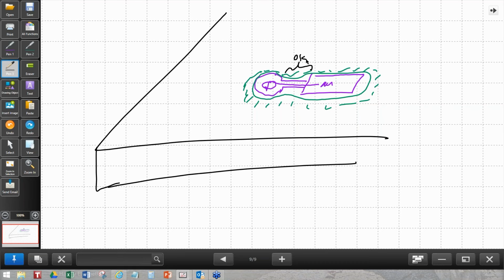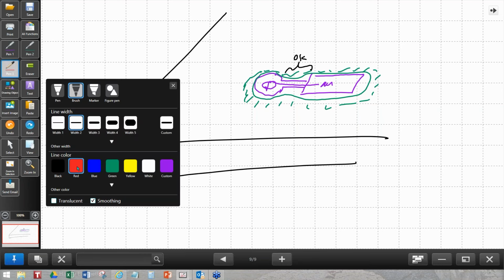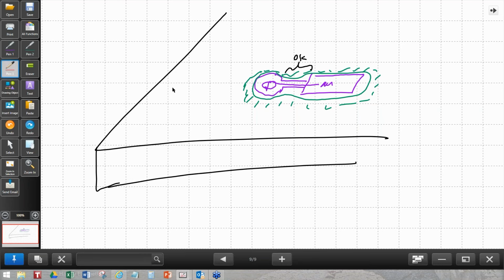There's two things you can do. Number one, after this is made, you can come back and conceivably conformal coat, i.e. put a little drop of epoxy or some other conformal coating mechanism over this hole before it's soldered.